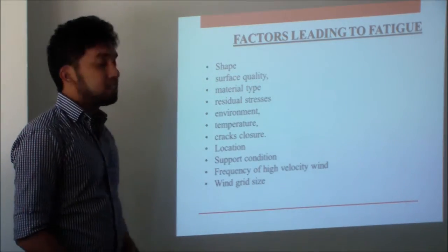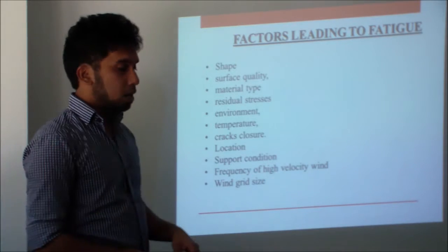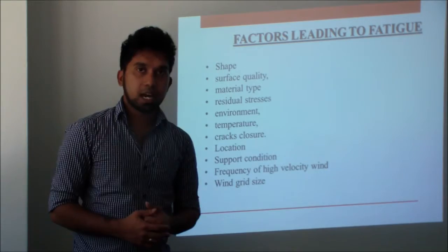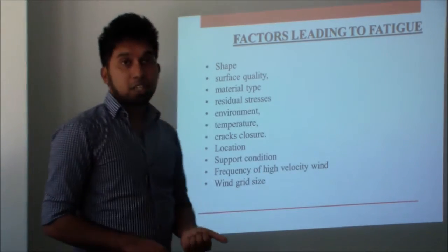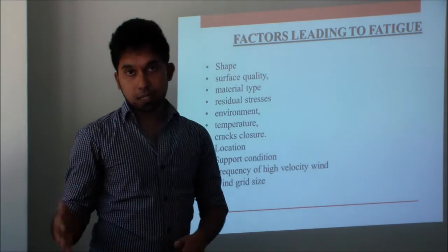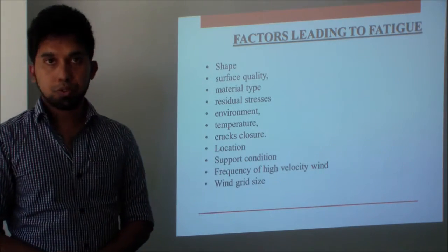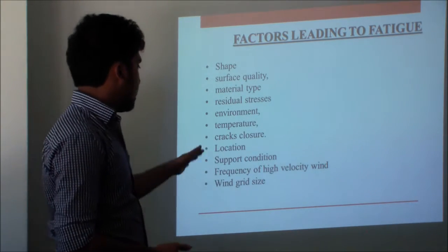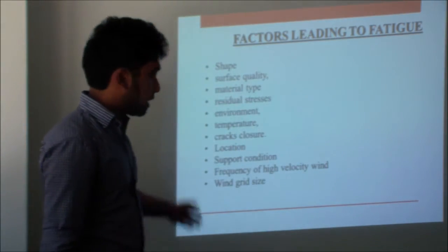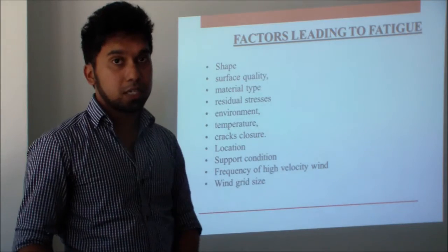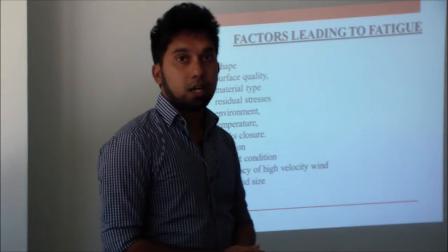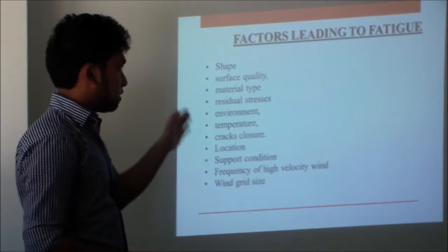The factors which can lead to fatigue are shape of the structure, surface quality, material type, environment, temperature, location. Wind grid size is another factor which can contribute towards fatigue. Then support condition is another factor. Frequency of high velocity wind is one of the important factors which should be considered while considering the topic of fatigue.